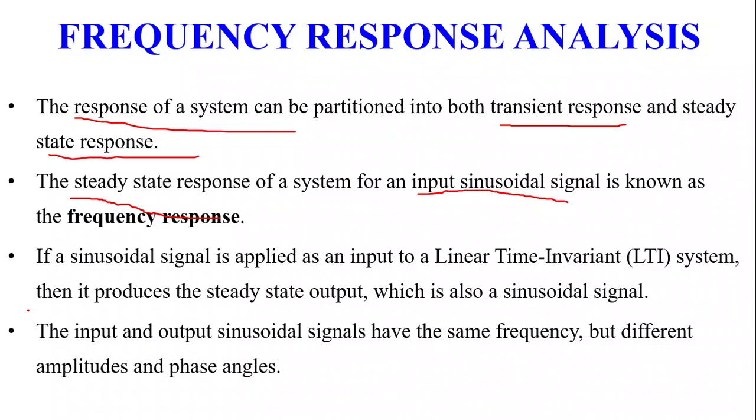How? If a sinusoidal signal is applied as an input to a linear time invariant system, then it produces a steady state output, which is also a sinusoidal signal. In frequency response analysis, we vary the frequency of an input signal over a certain range and study the resulting response.